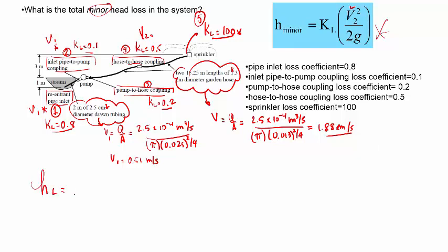for each pipe. So let's mention the components for P1, and remember these are the minor losses. So the velocity is 0.51, and we put it all in the basic units, so we don't have to worry. And then here we have 0.8, let me put it in the same order, plus 0.1. So the 0.8 is the KL1, and this is the KL2. And these are, of course, very small, 2 to 4 meters. Okay.